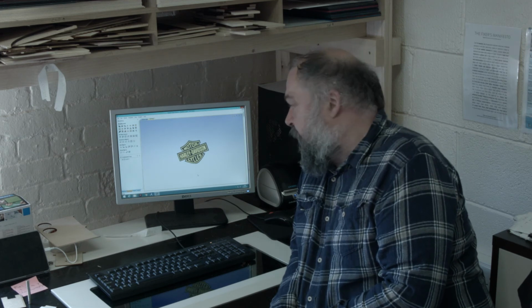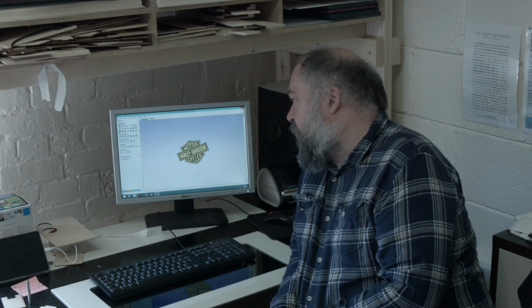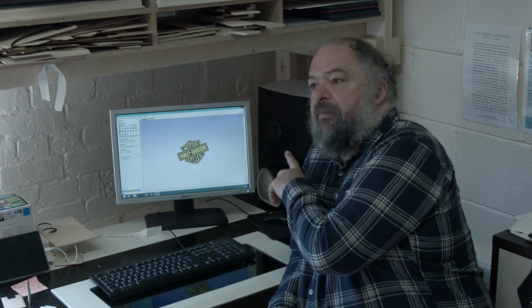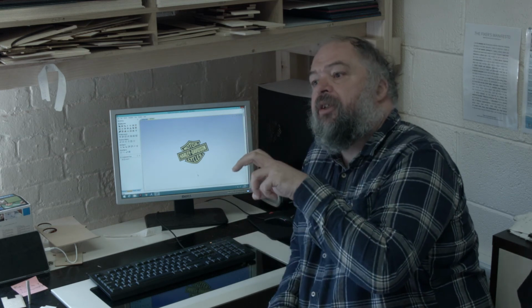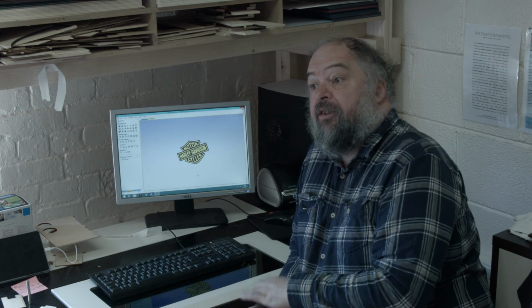It'll import ordinary true type fonts, so you can carve a true type font out as well. You can get a lot of interesting true type fonts as well. There's also a way to do inlays on it. You can do it using this V carve, the V toolpath. You can actually cut an inlay where it then slots straight into it, and then you just face it off. And it gives you a full inlay into it.